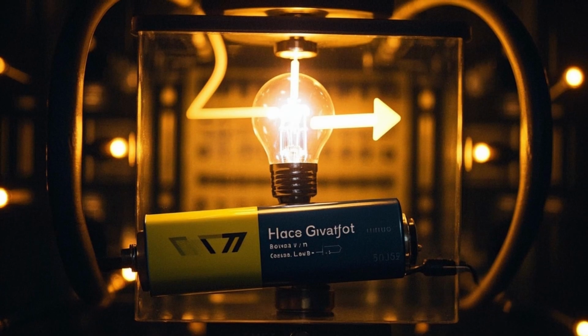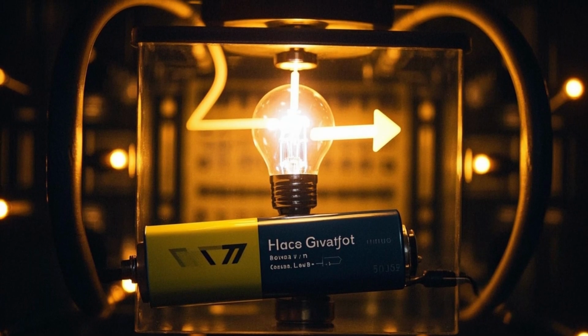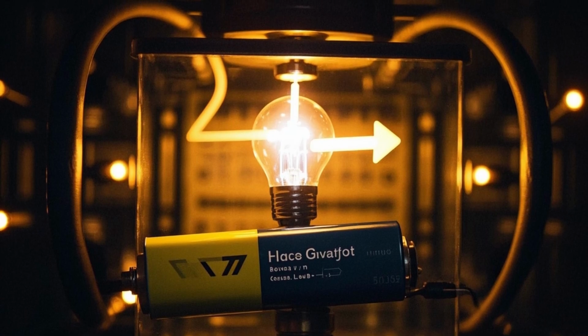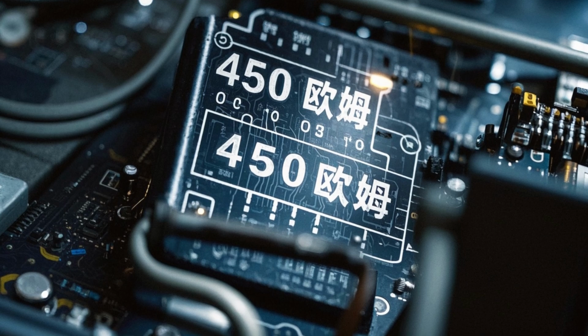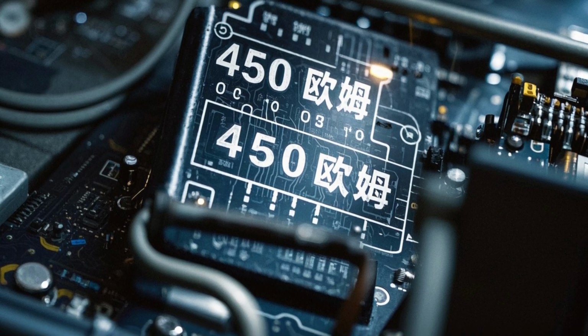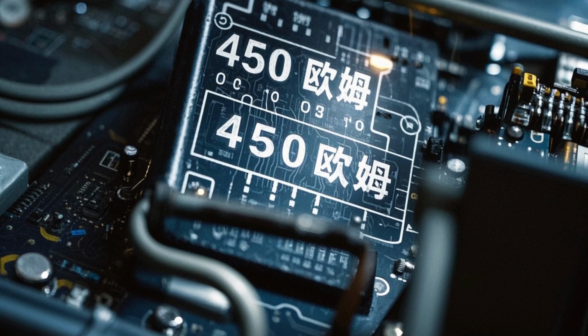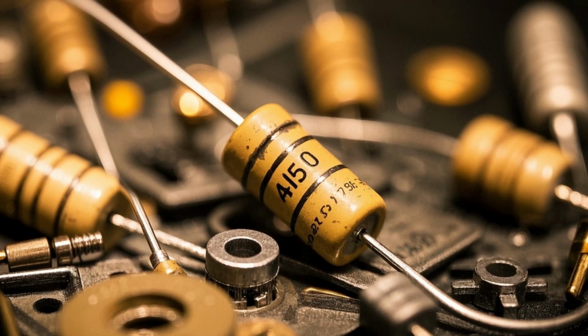Let us say we're building a simple LED circuit with a 9-volt battery and an LED. It needs a current of 20 milliamps or 0.02 amps to operate properly. We can use Ohm's law to solve for the resistance needed. So, resistance equals 9 volts divided by 0.02 amps, which equals 450 ohms. So we know we need a resistor with a value of around 450 ohms.